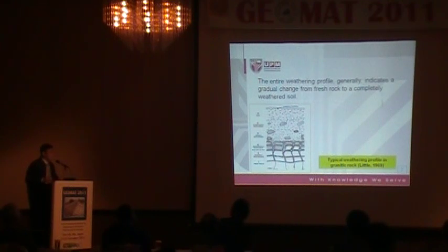But because our weathering is very deep, this soil layer can actually be very thick. If you talk about zones 1, 2, 3, 4, 5, and 6, up to zone 4 can be considered as soil, that can be in the range of many meters, and even up to probably 100 meters down. So that soil profile can be quite thick.